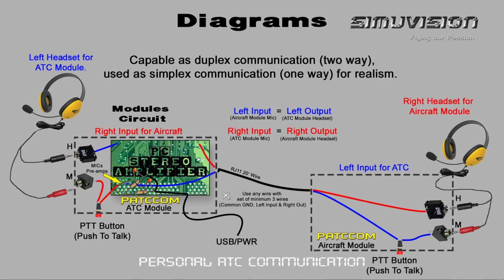Also, we have made our own mic preamps. This is very important. So it's a set of a capacitor and resistors. So please do make this preamp. It is very important. Otherwise, your microphone will not work, because this circuit is actually designed for already preamped music or anything you can connect, and then it further amplifies it.